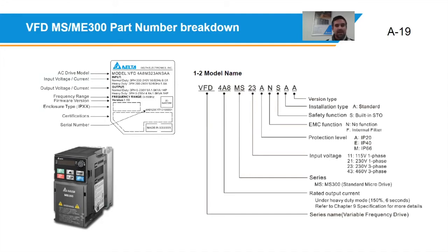I know that the C2000 variable speed drives can be a CANopen master to a network. And if I remember correctly, my colleagues would confirm with me, we've even done C2000 using a mod read instruction, reading another PLC or an IO block to extend the IO of that actual C2000.